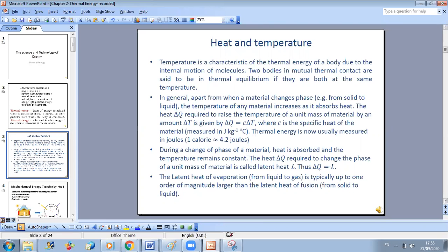Sensible energy, sensible heat? Yes, sensible heat, and the energy is in the form of kinetic energy. Because when you provide sensible heat, the result will be that you will have more motion of your particles. So you are giving them energy in the kinetic form. While when you have a phase change, okay, the energy you are providing will not be in the form of kinetic energy, because it will not lead to motion of your particles. It will do something else.